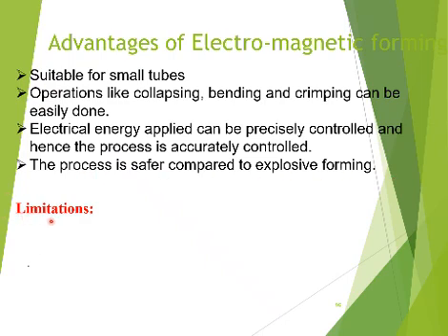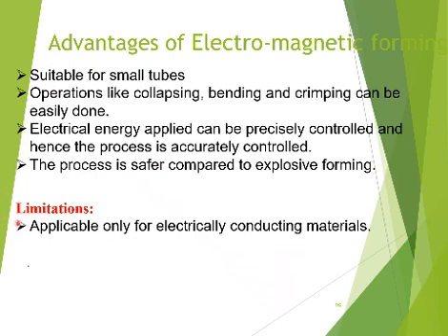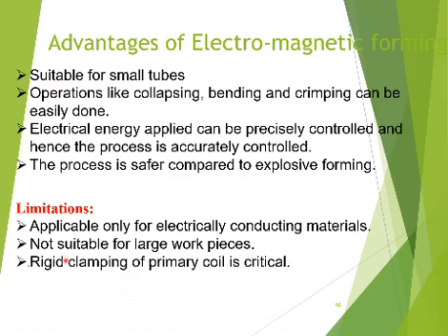Limitations of electromagnetic forming: it is applicable only for electrically conducting material. Not suitable for large workpieces. Rigid clamping of the primary coil is critical.